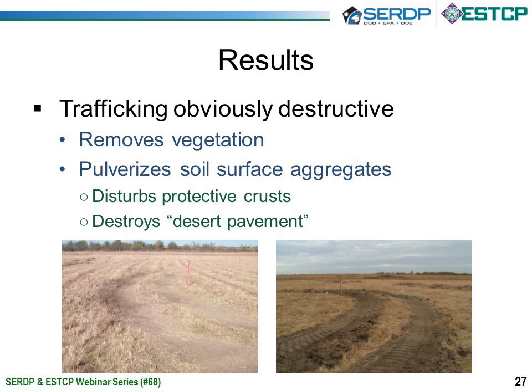In addition, fragile soils that may have built up a non-erodible protective crust over time or created a desert pavement on the surface are immediately disturbed and destroyed on the very first vehicle pass. In the absence of vegetative cover, these protective surfaces do aid in reducing a site's susceptibility to wind erosion. It takes significant time, often measured in years, for arid region sites to naturally rebuild this kind of surface protection naturally.